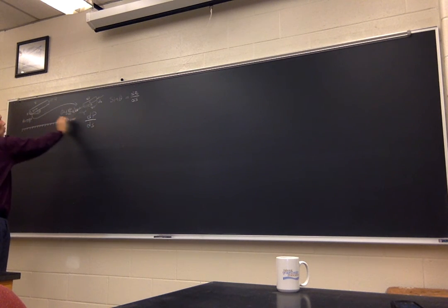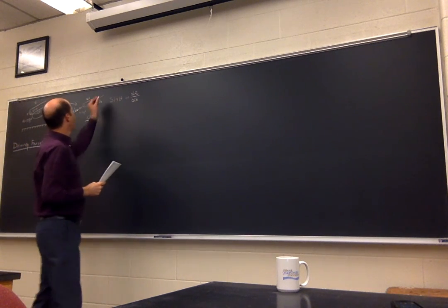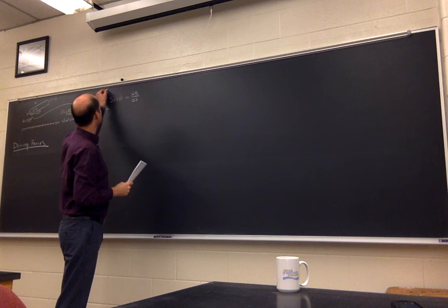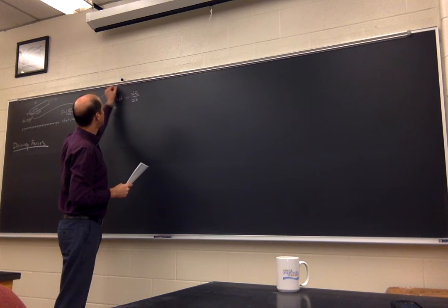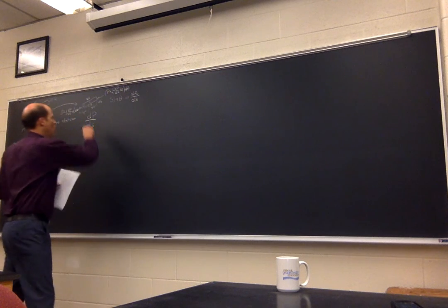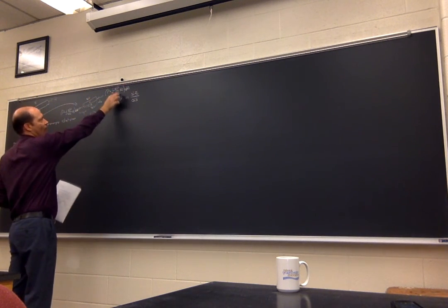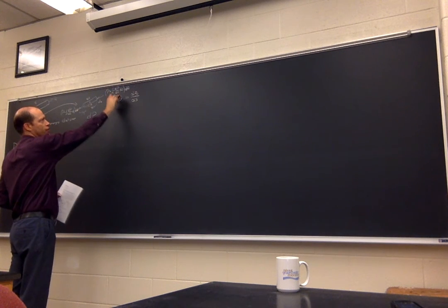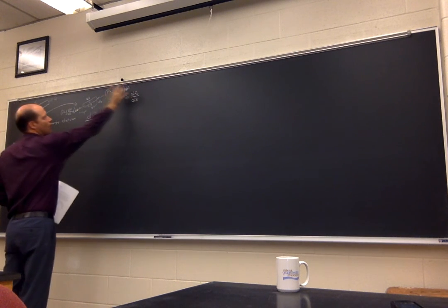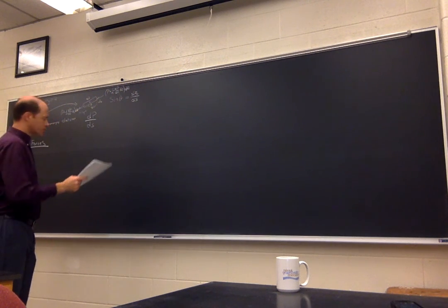So we have 1/2 of the change in the pressure going back the other direction, and up here we have a similar setup where we have P plus 1/2 dP/ds ds dA, because now we're going in a positive direction in our coordinates, and we're adding 1/2 of the total change in pressure across that distance and multiplying that by the area, which gives us the driving force.